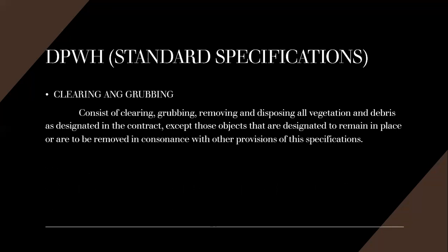Next is the DPWH standard specification. So, clearing and grubbing. This is the standard specification in DPWH. First is clearing and grubbing. Clearing and grubbing consists of clearing, grubbing, removing, and disposing all vegetation and debris as designated in the contract, except those objects that are designated to remain in place or are to be removed in consonance with other provisions of this specification.